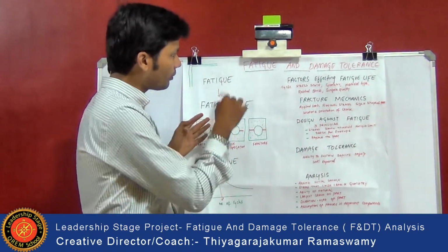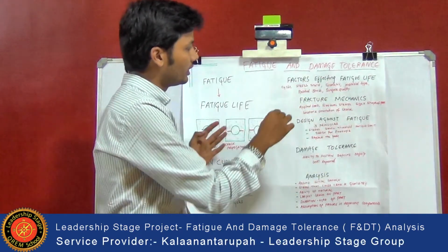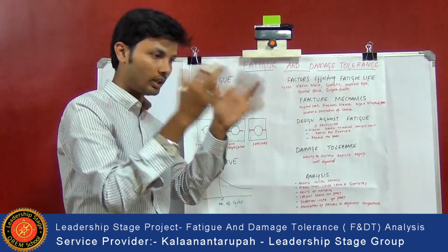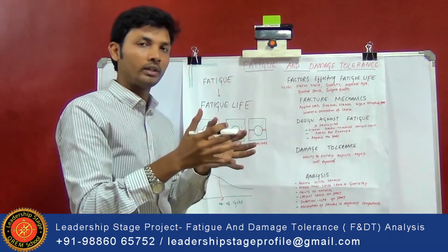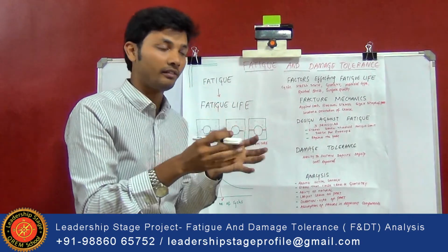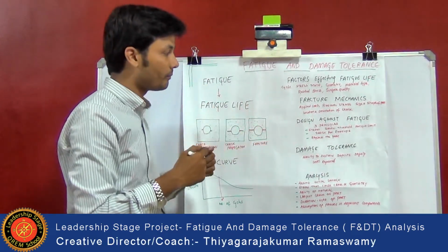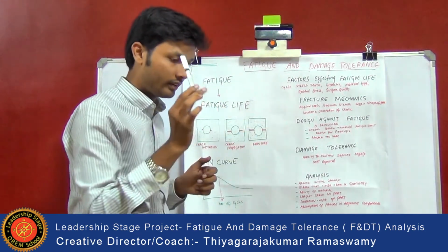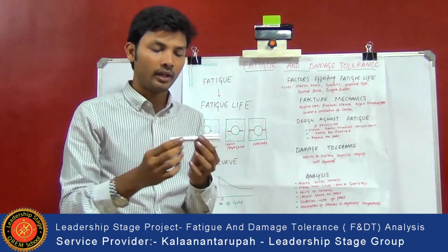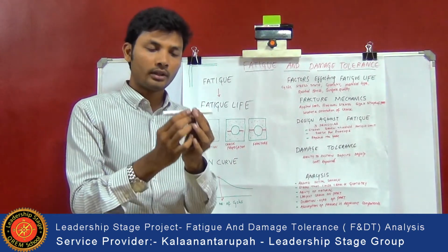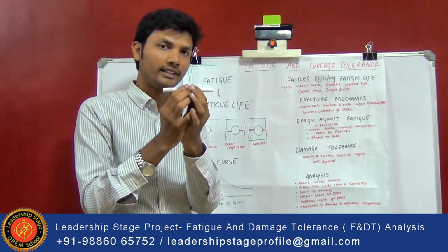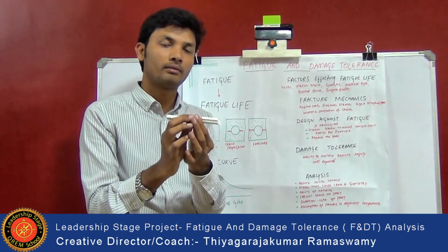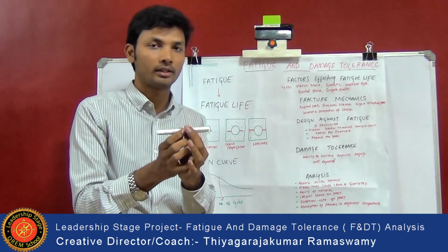So far what we have done is fatigue tolerance. Fatigue tolerance is nothing but studying fracture mechanics, where you can study how to increase the fatigue life, how to stop the cracking and everything. So even if you got the crack, even if the component has failed, the component should sustain its defect until that component is repaired. That is known as damage tolerance.